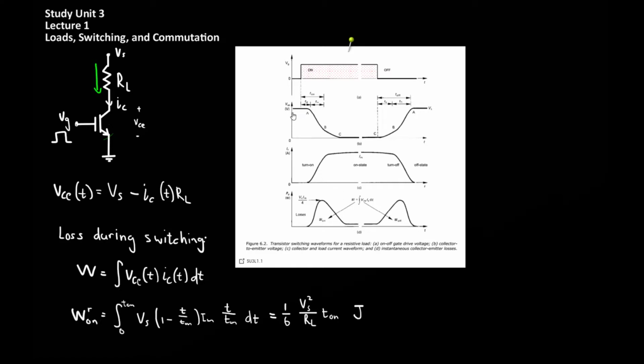From the plot, it should be apparent that the transistor here is not modeled as an ideal switch, and there is some transient as the transistor starts to switch and VCE starts to change. This is also true for when the device turns off, with a similar type of characteristic curve. From the graph, as VCE decreases, in other words, as most of the voltage drops across the load, the current flowing through the load will also increase until it reaches a steady state.